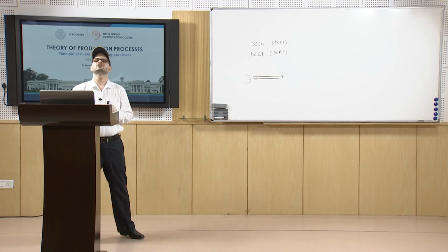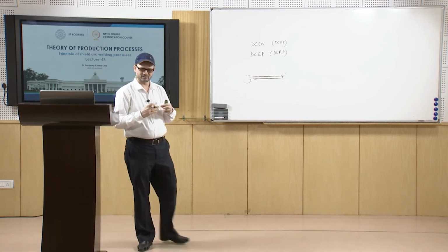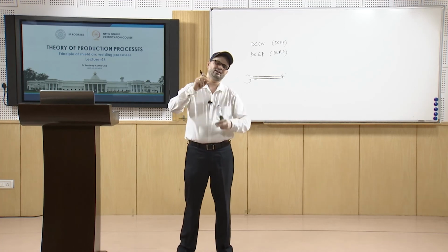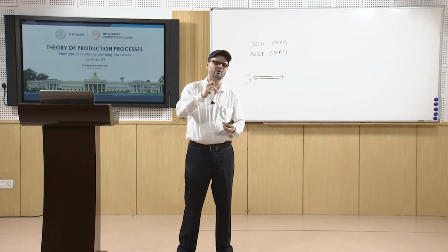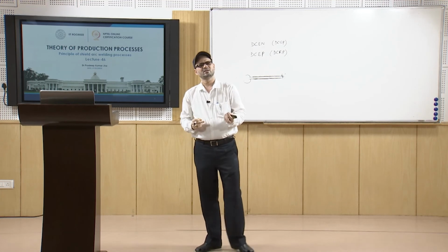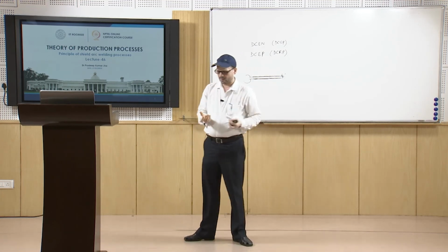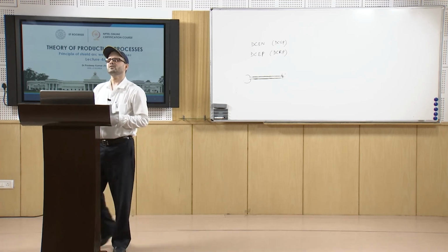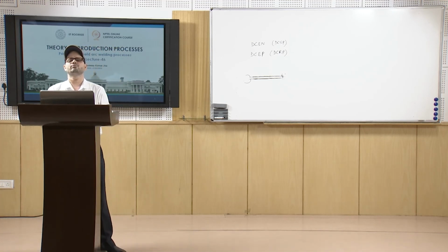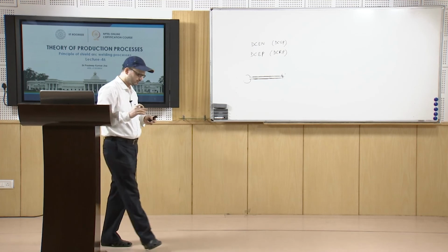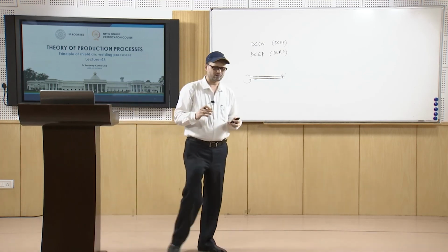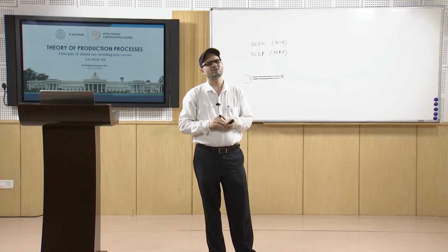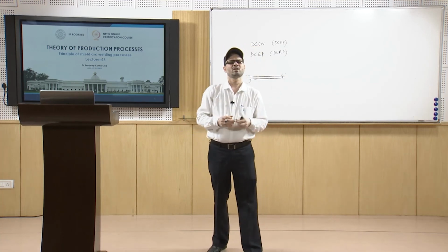Now, as we know, the principle of operation is again somewhat the same, because you have the electrode, which is basically the bare wire, and the work. So, this way you have the initiation of the arc, then you have different modes of welding. In submerged arc welding, you may have manual, semi-automatic, or machine type of processes.